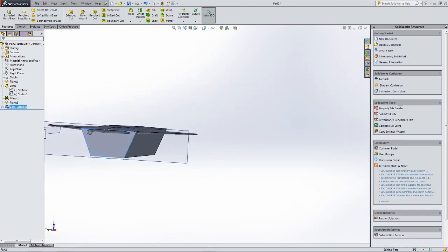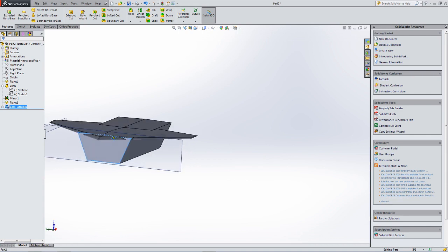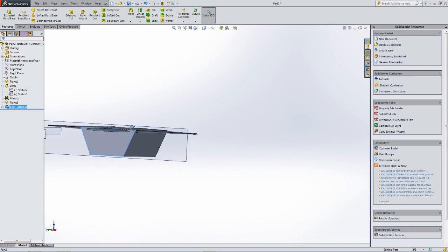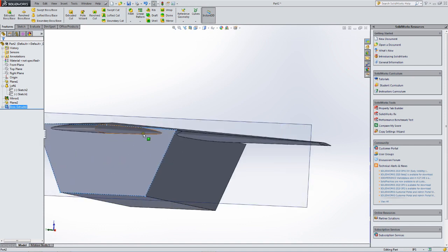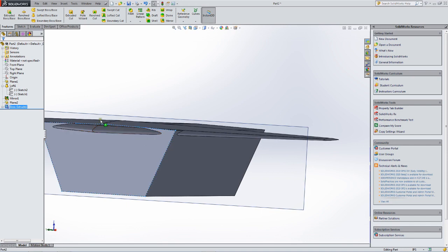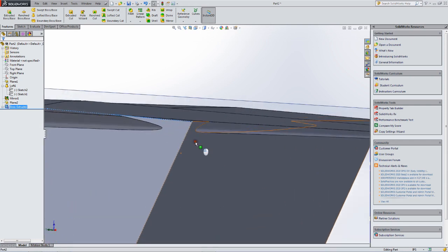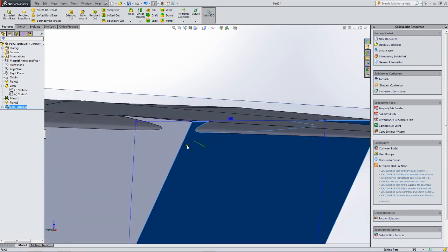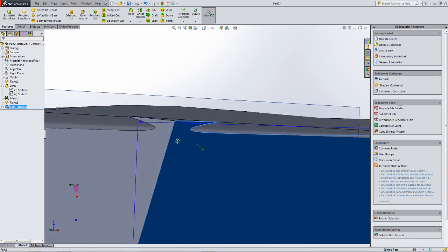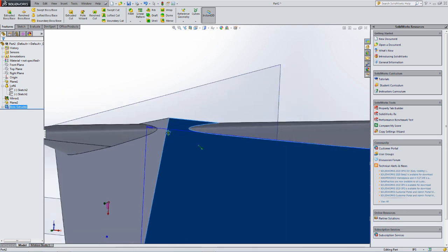And I'll do it by moving my sketch rather than the wing, because to move the wing I have to move 2 points, or 2 sketches. Move the fuselage, I only have to move 1. So I'm going to drop that down. I could measure how much. Here's one way to measure. There are other ways to measure, but here's one way.